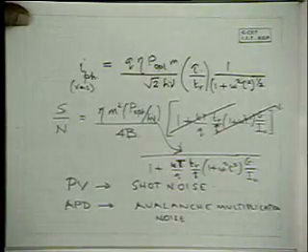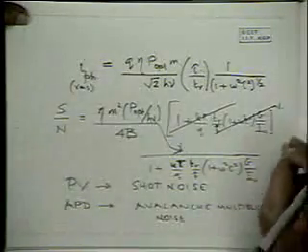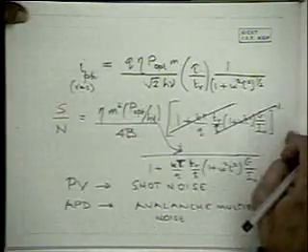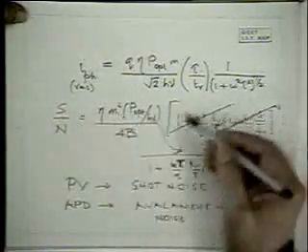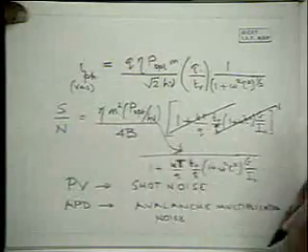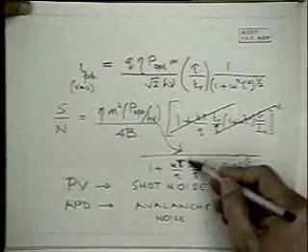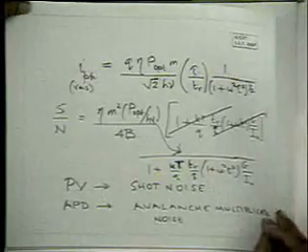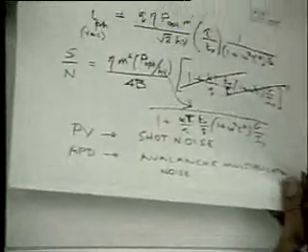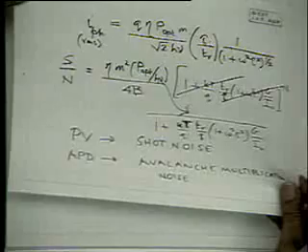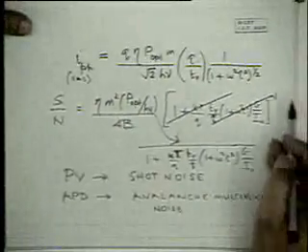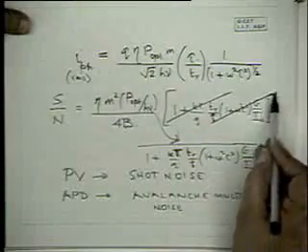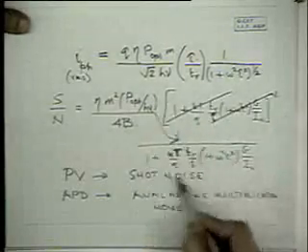And from the point of view of detecting weak signals, it's always our endeavor to try and maximize the signal to noise ratio by either increasing M or reducing temperature, reducing bandwidth, and some of the material parameters involved also. Yeah, this whole thing should be in the denominator, to the power minus 1.